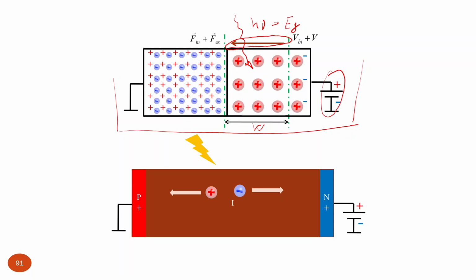So another option, if we want to have this highly resistive region, which is a depletion region with strong electric field, is to engineer the device in such a way that by definition we have this region almost everywhere. That is the case for this PIN photodiode. In this case you have highly doped P and N regions which occupy a small part of the photodiode, and the major part of the photodiode consists of intrinsic semiconductor with high resistance.